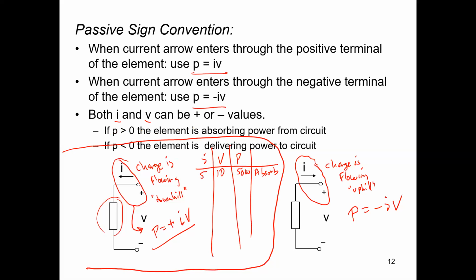Right? Means the battery's getting charged if that's the dead battery in a 2-battery circuit, right? But what if, when you hook up your voltmeter, you find the current is actually minus 5 amps, even though the voltage is 10 volts. What is the power? Minus 50. So what does that mean for that component? It means that's actually the good battery in the circuit. That's the battery that's providing the power. It's sending power into that circuit out of those terminals, right? So it's delivering power. It delivers power.